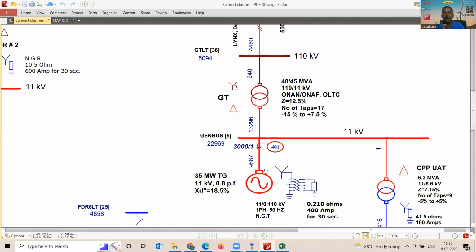So in cogeneration you can try both options. You can generate electricity first, and then use the excess heat for a process, or you can use the heat for the process first, and then use the waste heat to generate steam and then power. If you generate the electricity first and then use the heat for a process, that's called a topping cycle with respect to a cogeneration plant.